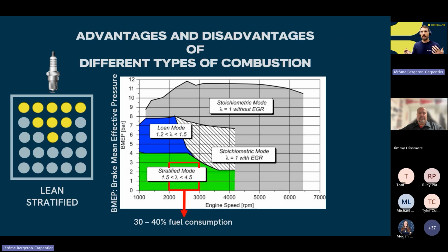So we are still doing some fuel economy with EGR since we are using those vapors or unburned HC and CO from the last combustions. And then we are running leaner in a way. We're just going to replace the fuel molecules that we would inject with those unburned particles.